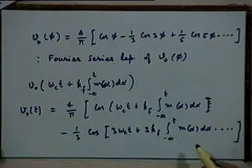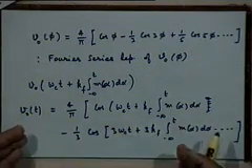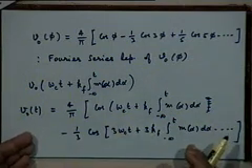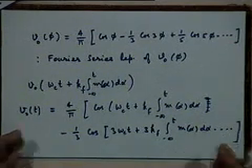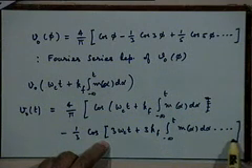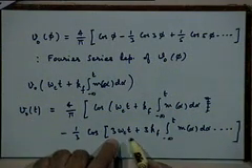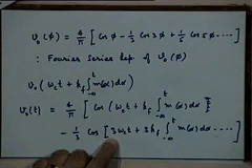Okay. So, this is a series representation for the output signal at the output of the hard limiter. And what are we following it up with? We are following it up with a band pass filter tuned to f c, and as you can see, all other components of the Fourier series representation of V naught of t, they are around 3 omega c, 5 omega c, and so on and so forth.